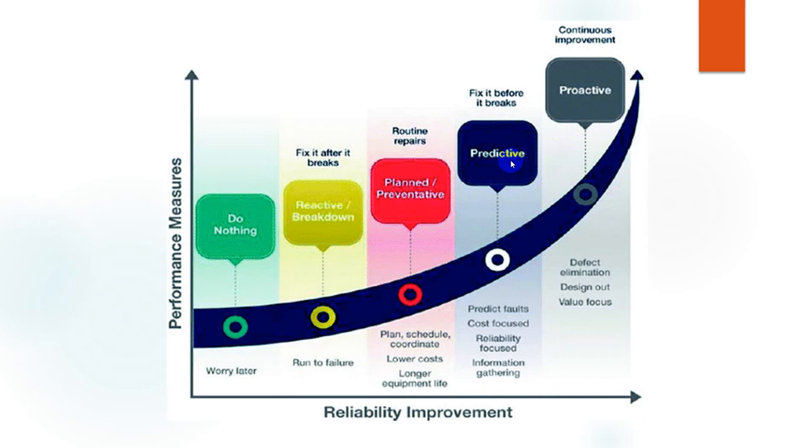Like in vibration analysis, you get early warning when you have a high vibration level, but exactly you don't have failure yet. What that means, you have early warning that you have a problem, you have a bearing to replace, you have alignment to adjust, you have balancing to balance it. Anything like this, you can arrange for this kind of maintenance before actual failure starts to take effect or starts to take place.